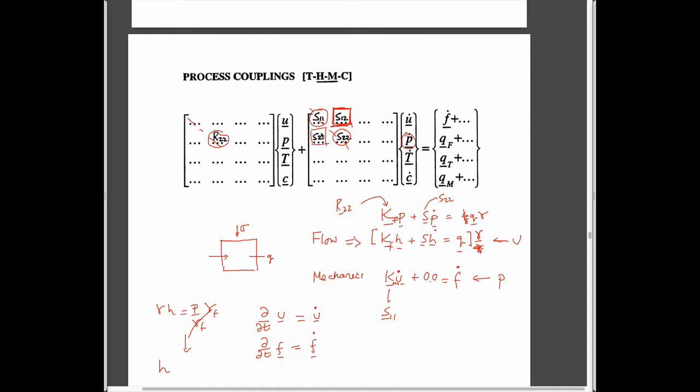But what we'd also like to get is to know how pressures might change over time to be able to feed back into that. If we know how the pressures change with time from this other equation, then we know how to be able to solve it. And so we have this, the conductance equation. We have this, the storage relation. We have now an expression which links the effects of deformation. And so what that really is, if you think about it, is if you prescribe some rate of change of deformation on the element, it's going to squeeze it like a sponge. It's going to squeeze the fluid pressure out of it.